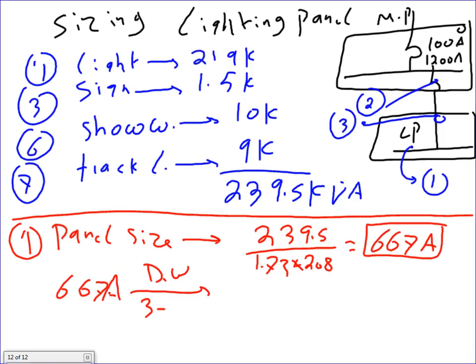3.13, I think, or 3.12 probably this one. What's 800? It's an 800 amp panel. So it should be 13, right? So 3.13. That will be an 800 amp panel. Done. So my panel is an 800 amp panel. Any question, guys? I have an 800 amp panel based on the calculation. Just the panel yet. We're not sizing the overcurrent protection device.